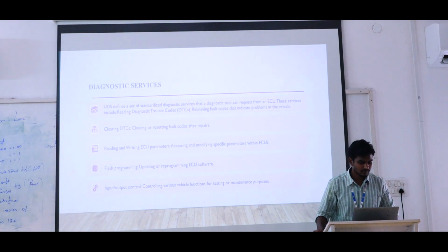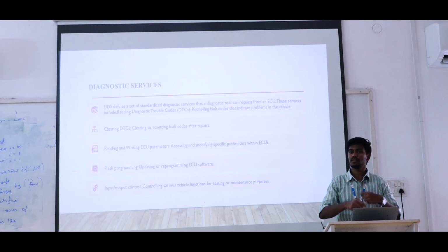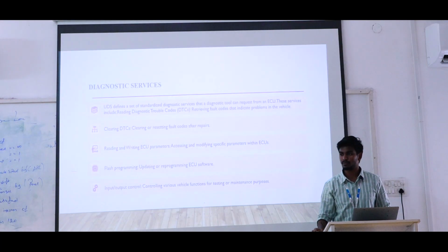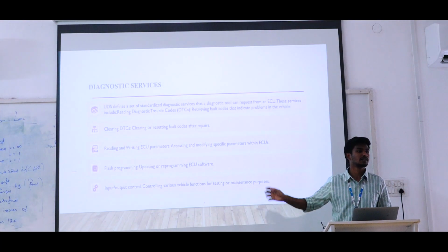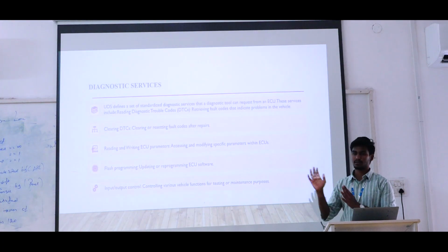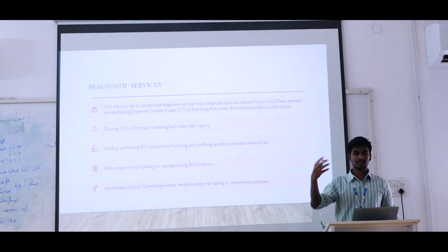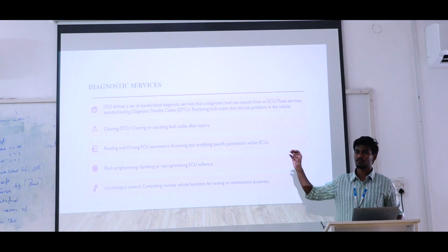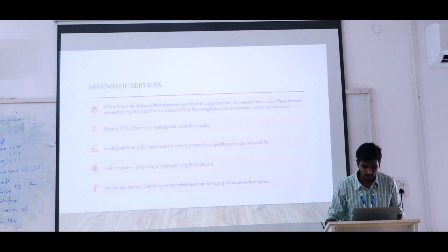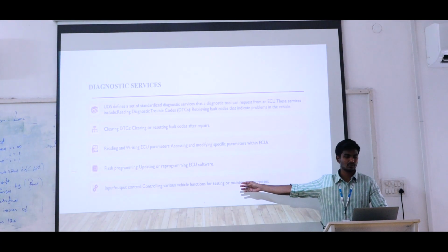So then we are able to flash the program and reprogram our ECUs. It is based on security purposes only. We are not able to easily diagnose all the vehicles. Before going to this diagnosis, it is enabled with some securities also, so we just clear those securities. Afterwards only we are able to reprogram the entire ECUs, and then do some input output controls, testing and other functions.